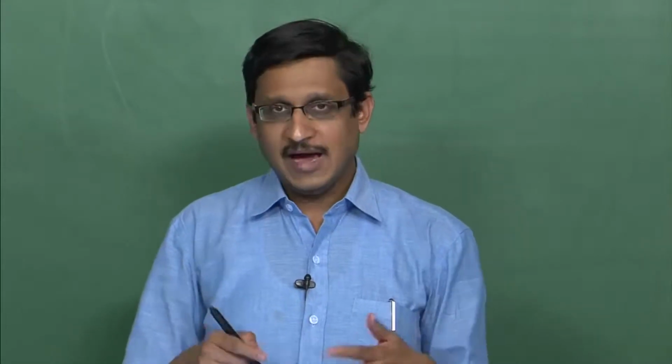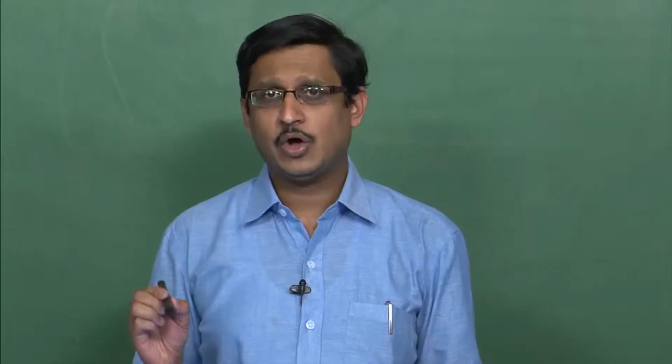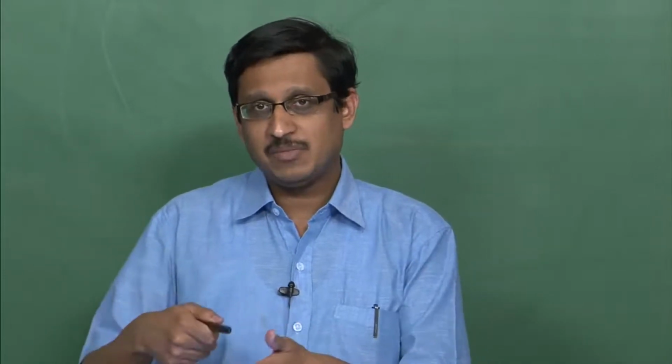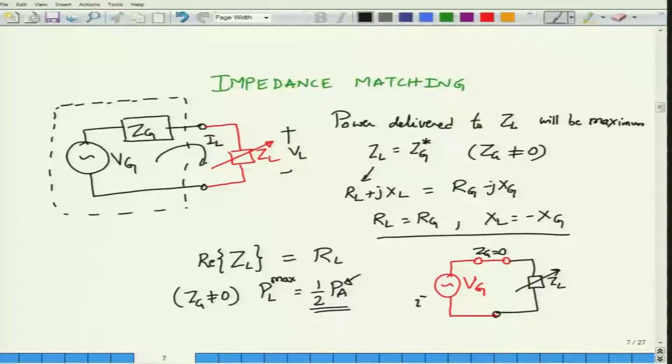Okay. So as I was saying, by some miracle, if the internal impedance were to drop to 0, in that case no matter what load you connect, you will always end up having the power dissipated, right. And that would actually give you the maximum power that can be extracted out of the source. Of course this source is an ideal source here simply because Zg is equal to 0. This is more of a practical source, okay. And when you look at the power that is dissipated in the ideal case, so here when Zg is equal to 0, the ideal load that I would like to connect would be any value of the load RL.